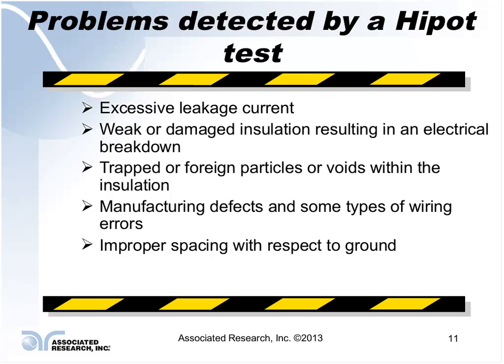Air is an insulator. If spacing is too close, you're going to get an arc over. It could result in the conductors or carbon tracking across the surface of an insulating material. So if you're jumping a gap, if you don't have adequate spacing, that's going to create a failure itself.